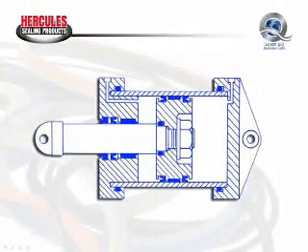Now, even static seals will have some movement within the confines of the groove. As pressure is transmitted through the fluid throughout the hydraulic cylinder, pressure will flow in this area here, push against this O-ring, and will deform the O-ring against the back of the gland.